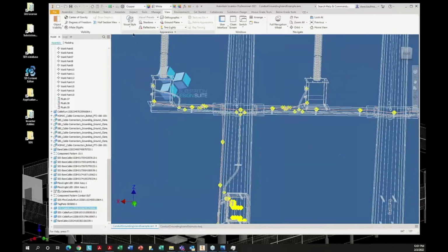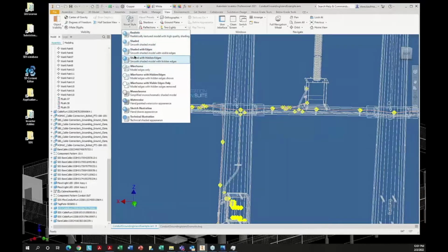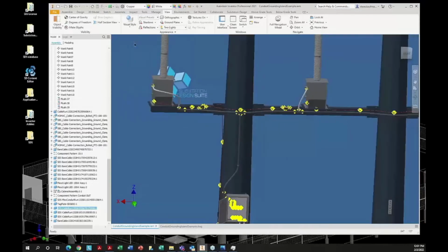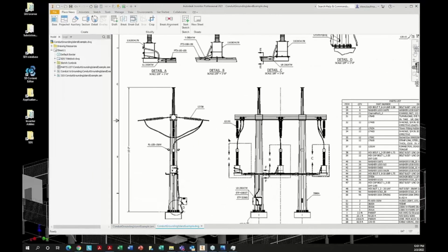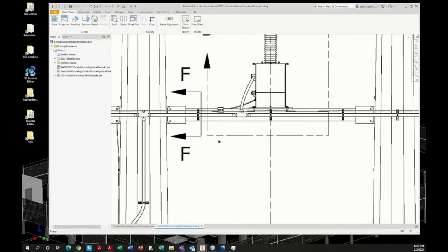So that's just running that type of stuff. You can run as many conduit cables inside that conduit run. The only issue, again, is it's going to run it down the center. So that's why this is going here. If you look at the cutaway here, this one, FF, I cut FF, so I've got a cable running through this one, and I've got a cable running through this one. So there's 2 cables in this piece of conduit here.